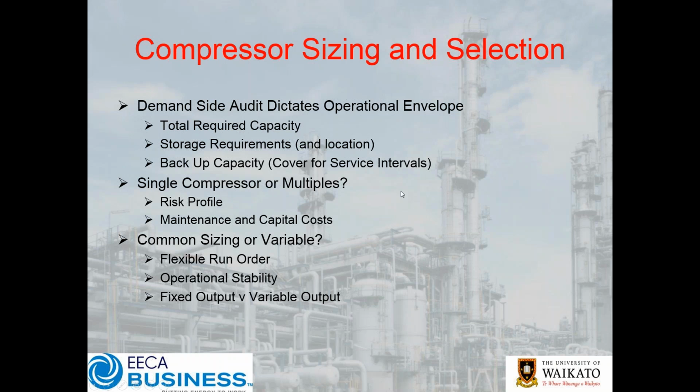Now, if you've got the plant off, then you can schedule your servicing in those windows, and that might not be a concern. You've got single compressors versus multiple compressors and how you then interface and control them. There's maintenance and capital costs to consider.